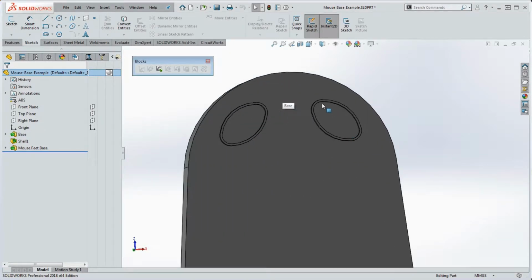What it is, you sketched these out on the top and then mirrored them over here. Didn't have them fully defined, which is probably kind of a problem because eventually they're going to stretch out and break on you. You want to make sure that everything is fully defined. And of course, when you get to the point where you're actually telling somebody how to make it, and you don't have any dimensions on it, then people are going to be scratching their head wondering, well, how big is that? What's the form like? So you definitely have to fully define it.